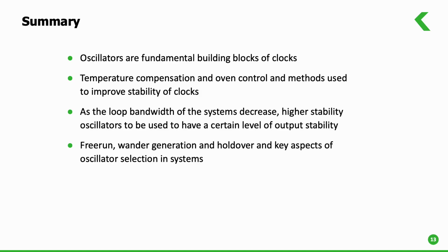Freerun, warmup generation, and holdover are the key aspects of the oscillator selection. Depending on the requirement of the physical layer, jitter and phase noise may also be considered.